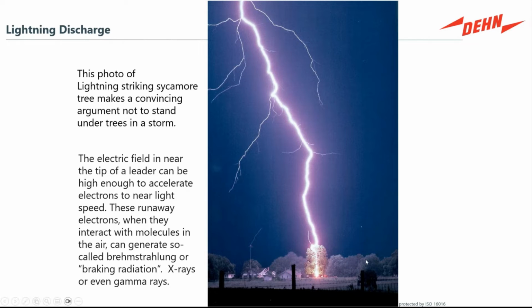but it gives you a really good visual of that electric field that's being propagated in the atmosphere, and charge is moving. The step leader jumps through the atmosphere, creating a tremendous electric field, finally attaching to Earth, either upward or downwards, lots of flavors of lightning, and then it becomes essentially a DC event where charge moves one way. It doesn't bounce off the ground and go back like an alternating current. It's a DC event with very rapid rise and decay time, but it essentially moves one direction, equalizes the atmosphere for that moment, and gets ready for the next strike.